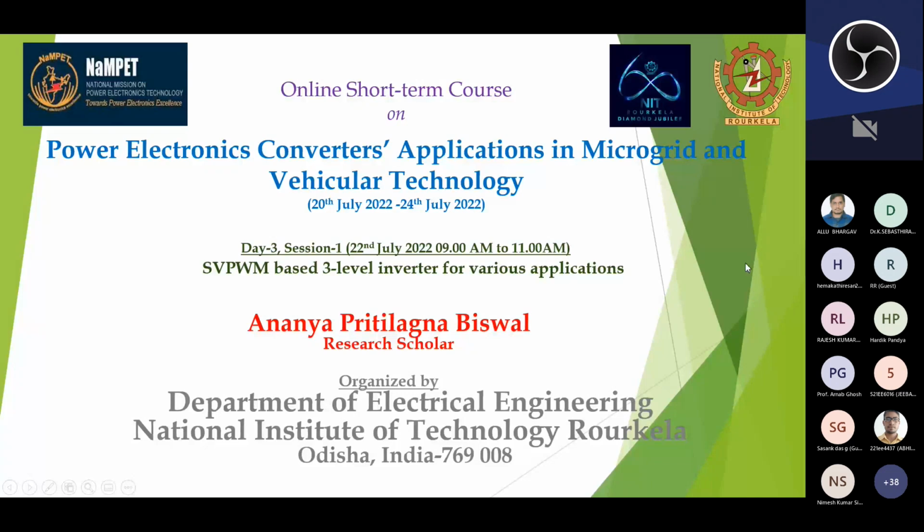Good afternoon, everyone. I am Ananya Pritilagna Biswal. My research project is based on SVPWM based 3-level inverter for various applications. A 3-phase VSI is the best way to provide variable voltage and variable frequency through AC drives. To get the variable voltage and variable frequency supplied from the inverter, various pulse width modulation techniques are used, like carrier-based sinusoidal PWM and space vector PWM, which are the most practiced PWM techniques.